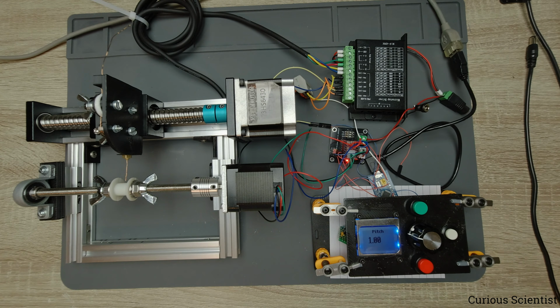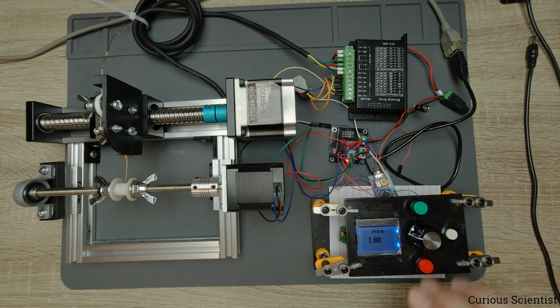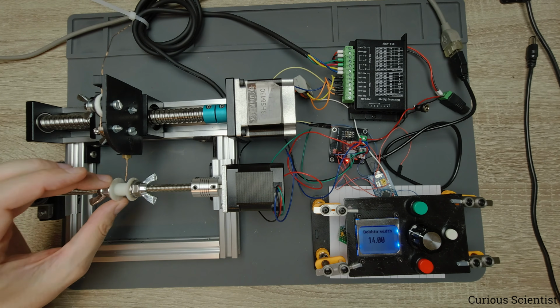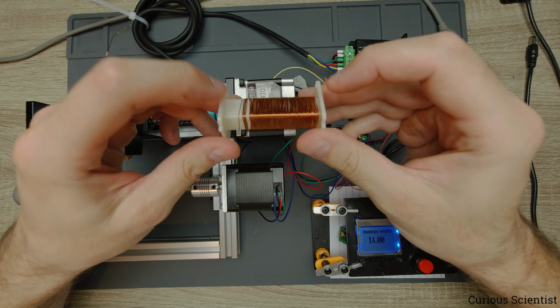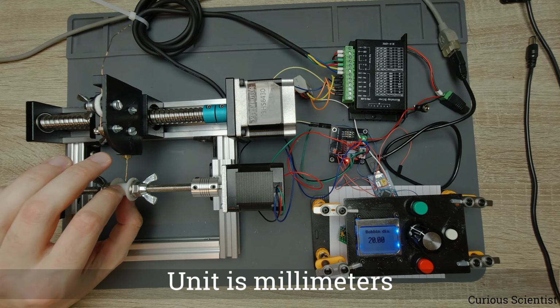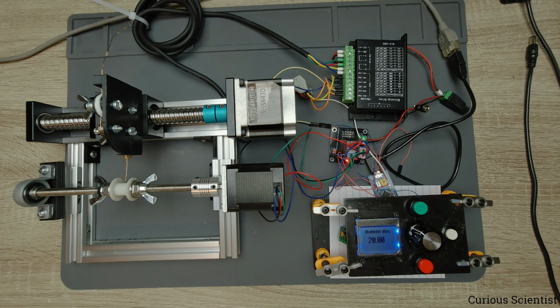And then we have the pitch, that's not yet implemented, but I will do that. So if you want to have a less dense coil or some fancy geometry, then you can change the pitch, but that is not yet implemented. And then we have the bobbin width, which is the width between these two larger diameter pieces. Or if I can show it on this, so between these two things. And then for this it is 14 millimeters. And then we have the bobbin diameter. So that, yeah, the diameter, it's not relevant for the feeder, but it's relevant when you want to calculate the wire consumption. So that's why I wrote this, because at the end I can calculate the total length of wire